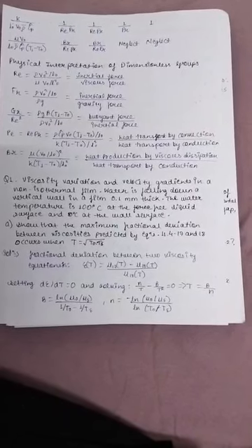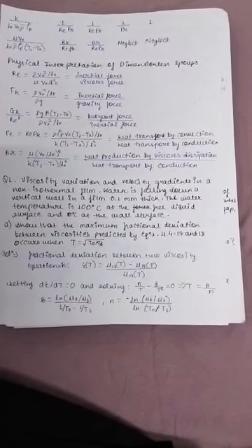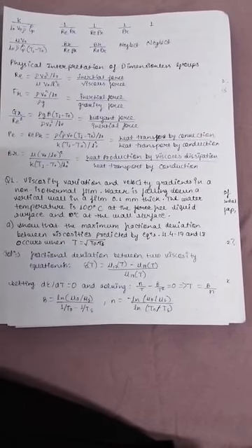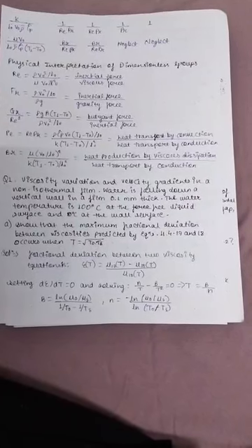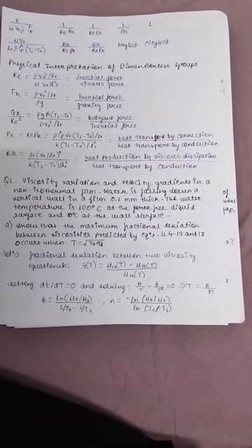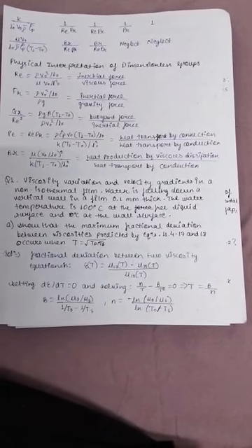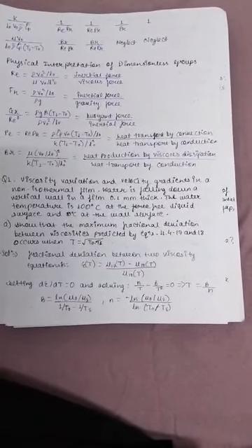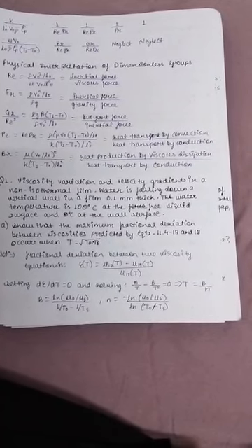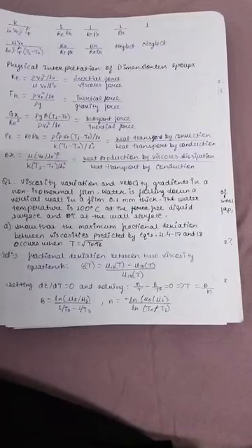Peclet number Pe equals Re times Pr equals rho Cp hat V naught (T1 minus T naught) over L naught divided by K (T1 minus T naught) over L naught squared, which equals heat transport by convection over heat transport by conduction. Brinkman number Br equals mu V naught squared over K (T1 minus T naught), which equals heat production by viscous dissipation over heat transport by conduction.